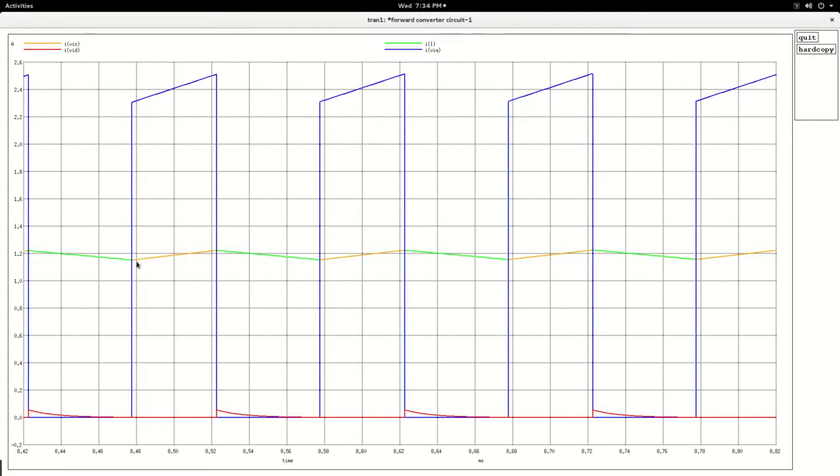You see that this inductor waveform, the part when the switch is on, is the same which we are measuring as the secondary current, and that is actually what is reflected to the primary. Now the average of the inductor waveform is I naught, and that will come as the flat top equivalent of the primary switch current, which is N times I naught. So the primary switch current's flat top equivalent current will be N I naught in this case.